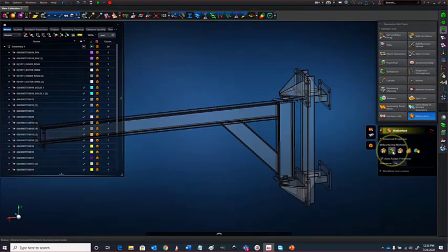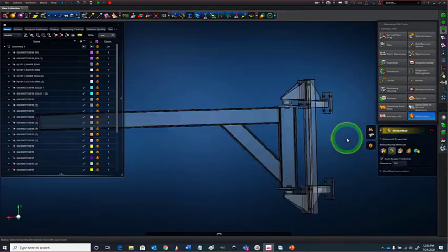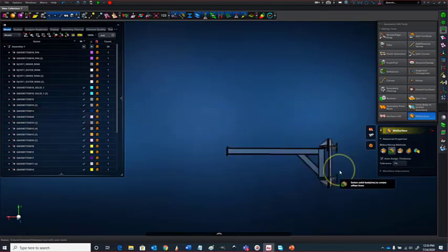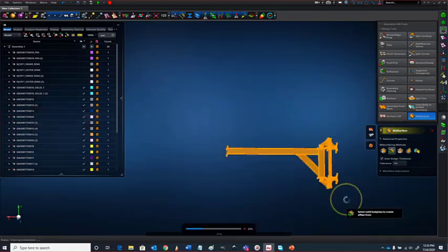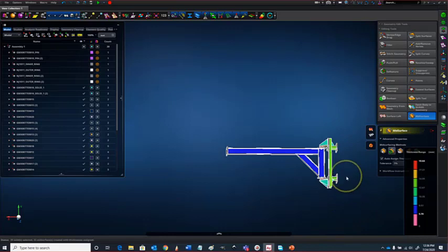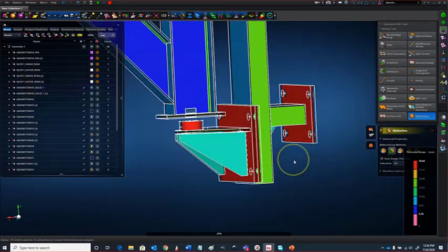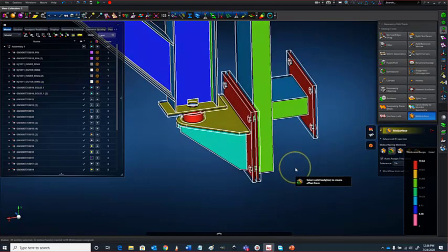I always use the auto mid surface thickness tool, even though it's actually only developed for components that have uniform thicknesses. This is always my go-to tool, and only when something is wrong or didn't work out as well as it should, I'll move on to one of the other options.